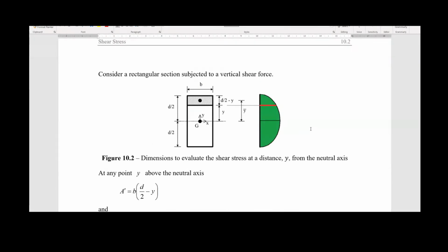In here, for example, you have the distribution of the shear stresses for a rectangular cross section, which is parabolic. So this means that we start at the extreme on top of the beam, where we know that the bending stresses are maximum, with a zero shear stress that will increase with this parabolic function until it reaches the maximum in the middle, exactly at the position of the neutral axis, where the bending stress is equal to zero, remember? So we start discussing the relationship between these stresses, because these stresses act on the cross section altogether, remember that.